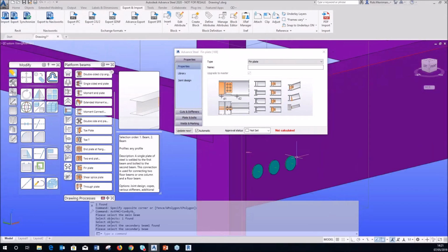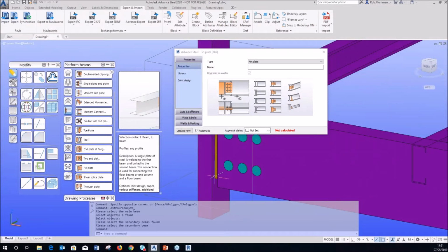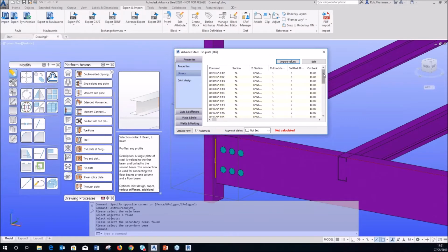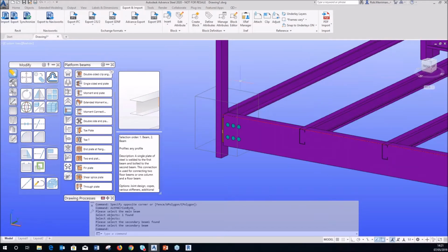Last week I was setting this up and playing around with different things. All the settings that I changed in Revit, I set up last week in Advanced Steel, and saved in the library. If we look at my library entry, there's an RM 250 by 70 by 3 channel with the 100 by 50 box section. If Advanced Steel finds those two sections, it will automatically apply that connection, so I don't have to go through the dialog and set it up. That will work on every project where I've got those two elements.